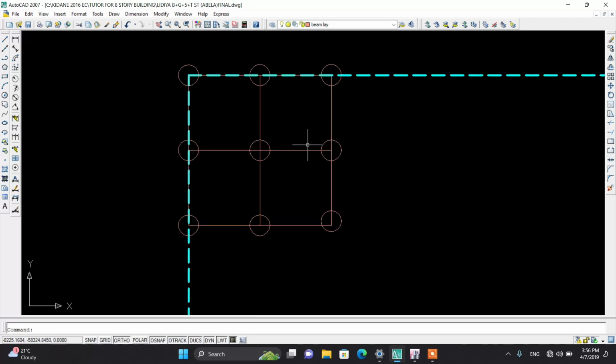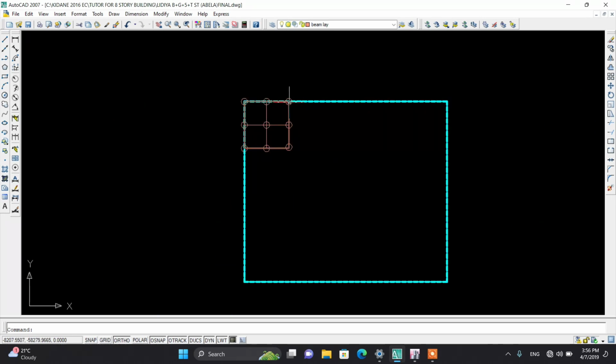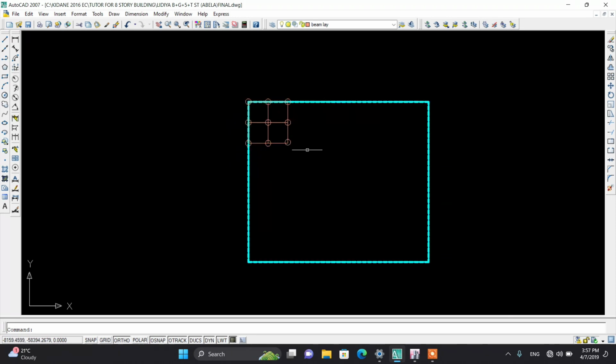This is the reason we mesh the slab: to increase the number of equations and to get every load, every movement and shear at every point of your building or your panel, as I showed here.